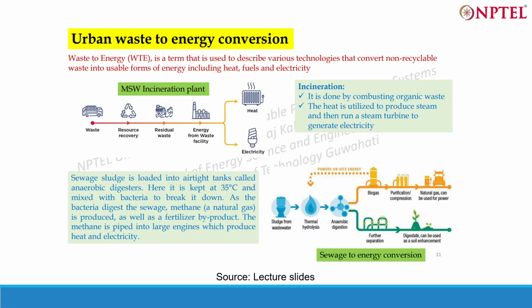Whatever is converted to methane is biogas, a kind of gas whose major components are methane and CO2. Whatever is left out is a mixture of the material and water, that is a slurry or digestate. Okay, that has a good fertilizer application, because the NPK values are good in that digestate. The methane can be used for various purposes, like natural gas utilization. Natural gas is basically methane, 95 to 98% methane.